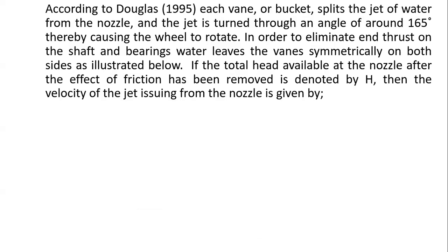Okay, now here we start with, first of all, the delivery. You will notice that when water is falling from a height, to know how much velocity is being delivered, you use this formula, V equals CV square root of 2GH. This CV is the coefficient of velocity.